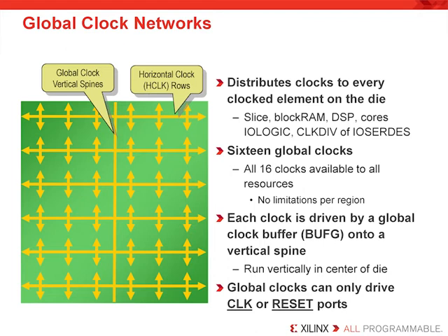The dedicated clock pins allow for the input clock to route to the center of the device where the CMTs, or clock management tiles, are located, and then connect to the dedicated global routing resources, which are accessed with a BUFGMUX primitive. This allows the clock to distribute throughout the die, effectively on a big fat wire.